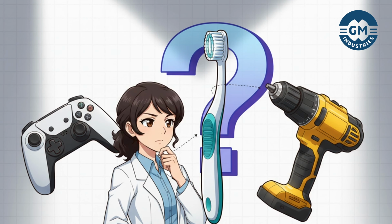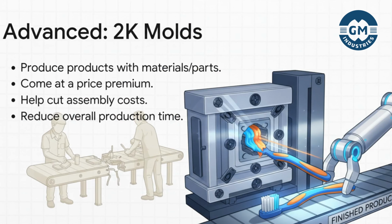Okay, so that covers single material products pretty well. But what about more complex things? Think of a toothbrush with a hard plastic handle and those soft rubbery grips. How are those made all in one go? That's where you get to the next level. An advanced tool called a 2K mold. It is engineered to inject two different materials in a single cycle. Now, these molds are definitely more expensive to create, but they can be an absolute game changer. By producing a finished, multi-material part in one shot, you eliminate entire assembly lines, which saves massive amounts of time and labor costs down the road.